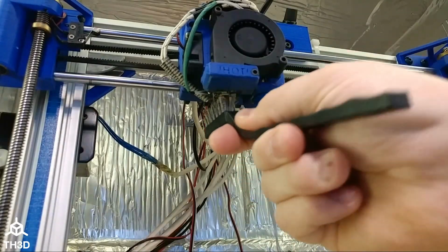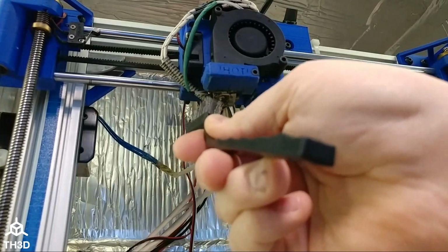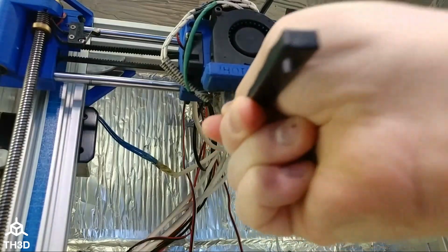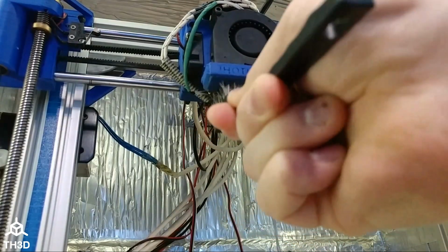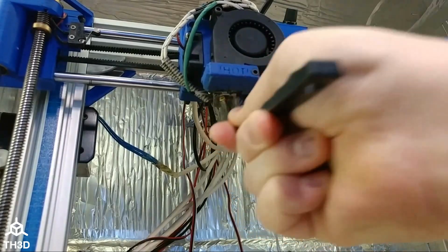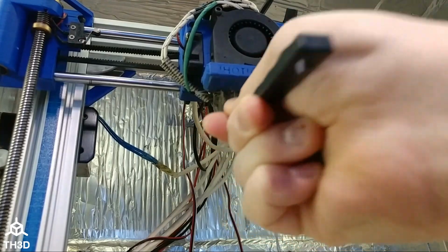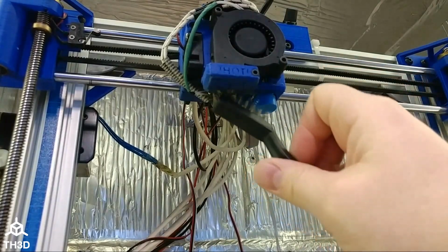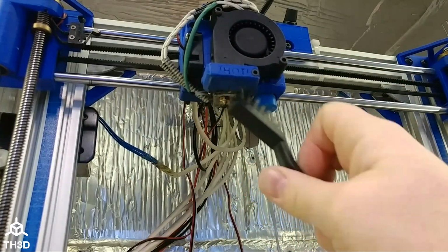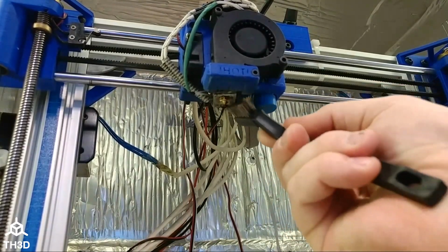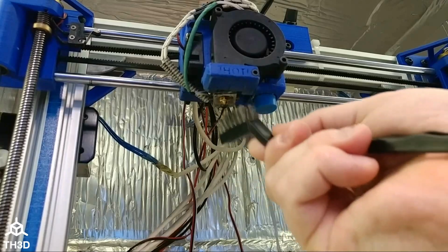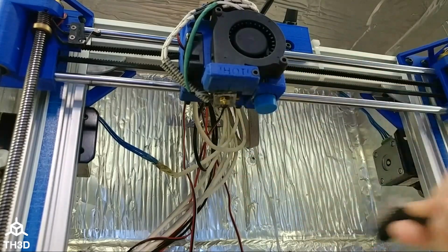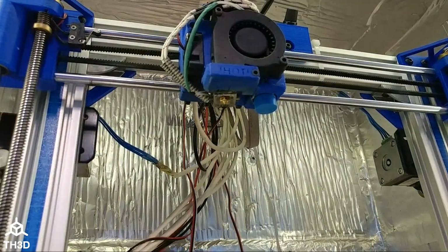So when you're cleaning your hot end, stay away from this side, because if these bristles touch the heater wires and get up in there and touch your thermistor, your board's going to get fried. So just go back and forth. Don't press too hard. And then I'll usually try to get up a little bit in here and just get everything I can off the block. That's pretty clean now. You can see that.